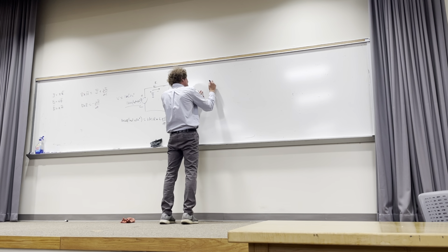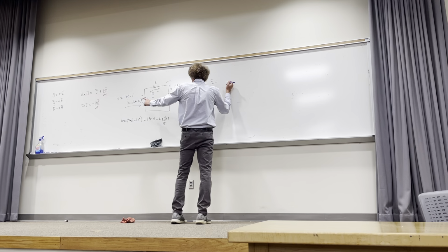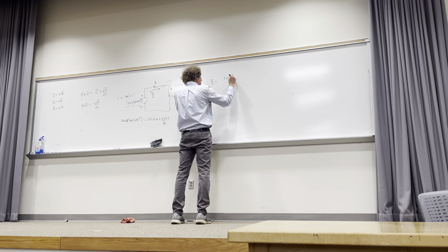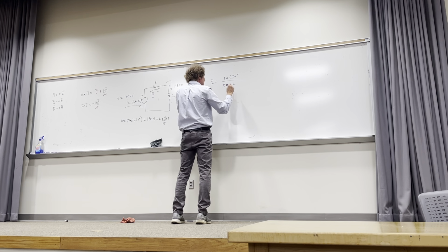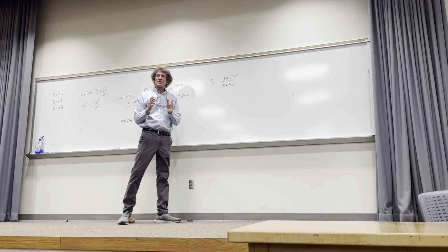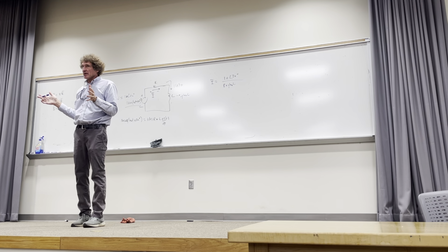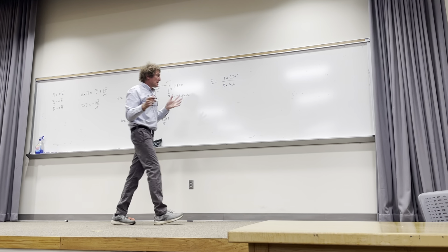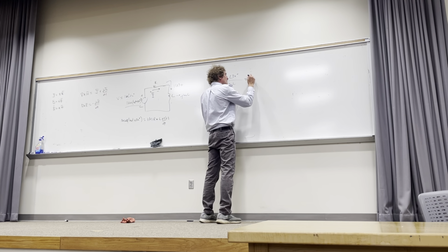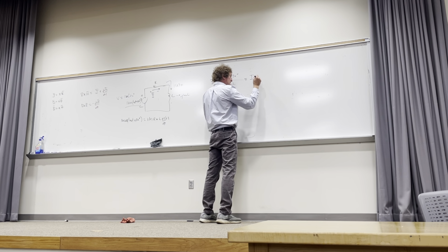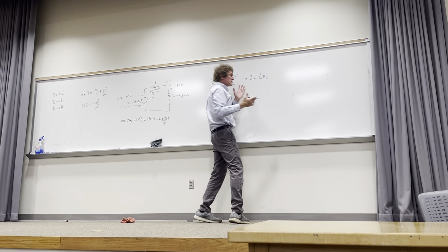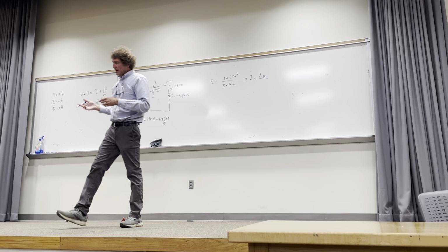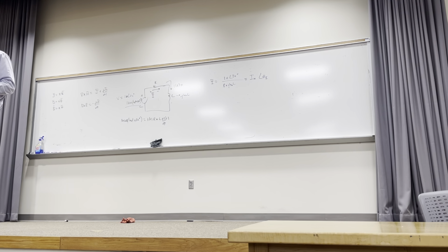So if I wanted this I phasor, I would say that would be this voltage, which would be 10 at an angle of 30 degrees over R plus j omega L, or omega naught L. Do y'all agree? And we know that's going to be a magnitude at an angle. So I can say this is some magnitude, I'll just call it Im, and it's at an angle, I'll call it theta I. Do y'all agree with this, class? If I give you omega, R, and L, you can give me exact values.